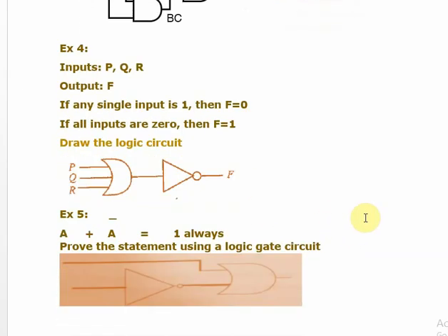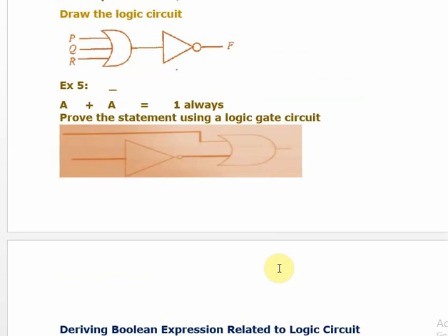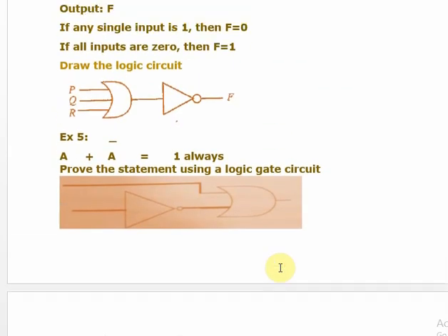So it's very simple. Here you take an OR gate, feed A here, the same A you are feeding here, you are putting the NOT gate, then this become A bar, no? Now you see, whatever the value you put here, 0 or 1, always you get 1 here, right? They are directly asking to implement the circuit, right? Now it is very clear,